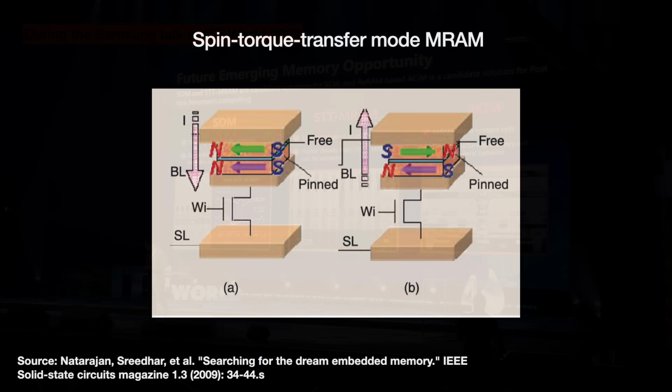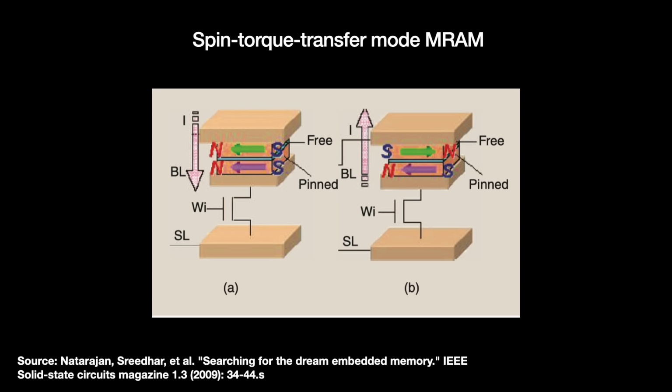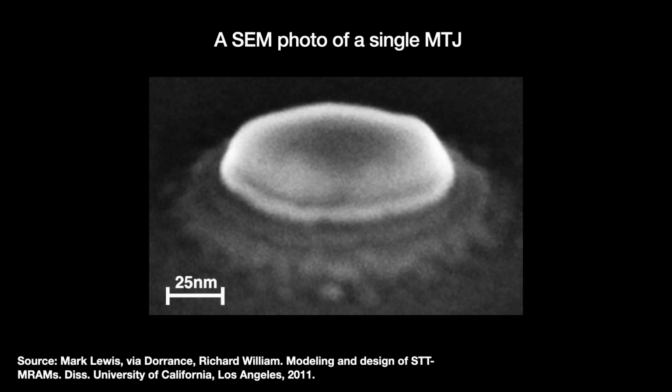Despite being a non-volatile memory, you can write to it in less than 10 nanoseconds, which is DRAM-like speeds, and far faster than flash memory's 20 to 100 microseconds. And unlike flash memory, the cells have very good endurance. The biggest challenge involves things on the manufacturing side.